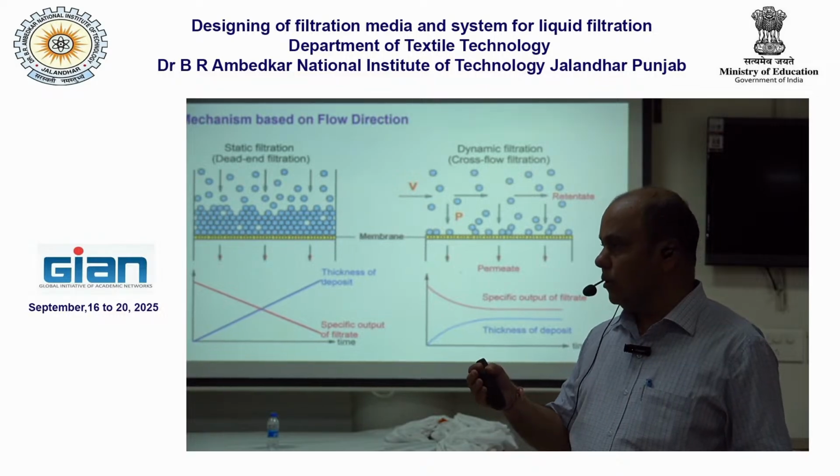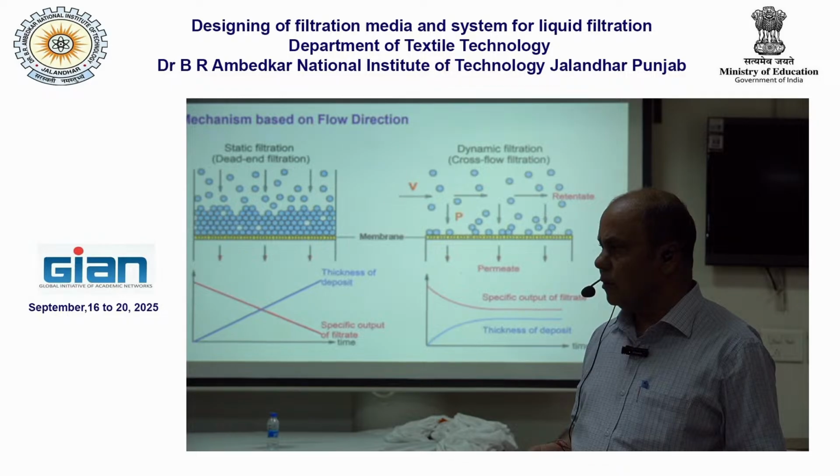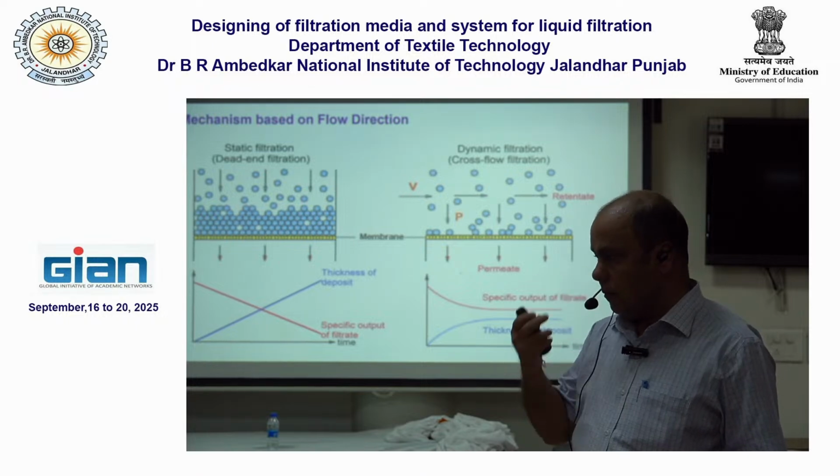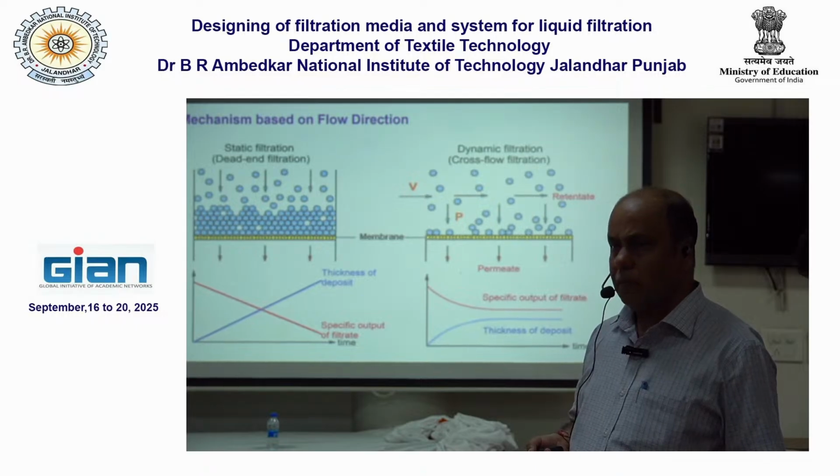No, sir. So here what happens in case of RO, reverse osmosis, RO removes all the ions, so TDS will be 0. But we need around 100 or 200 TDS. So what happens? They bypass another stream, and in the other stream RO is not working at all. So over there we use UV filtration, so bacteria can be killed. I hope.